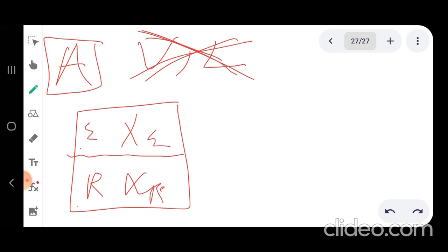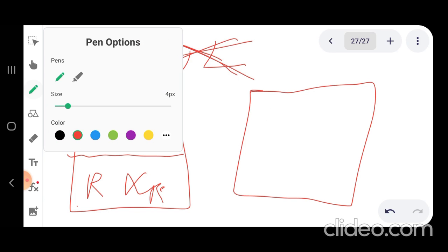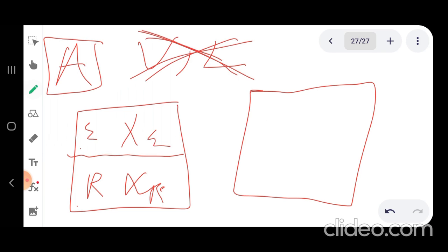So we can draw the same diagram, but instead of X and Y, we will draw it between XR and XE, the raffinate composition and extract composition.